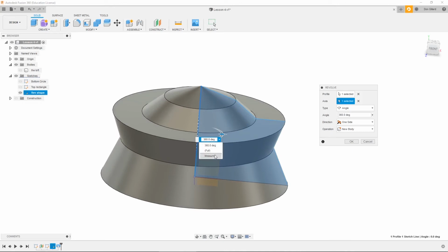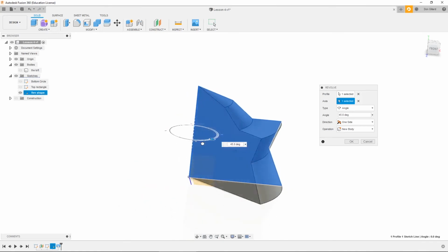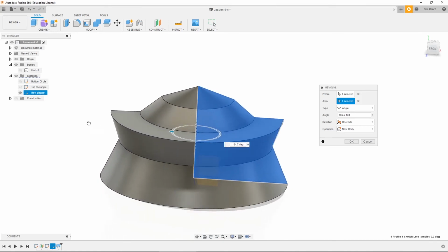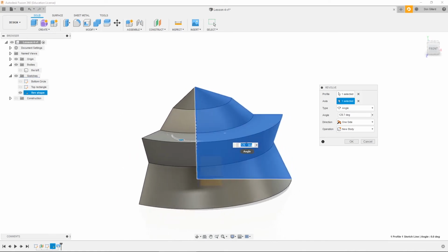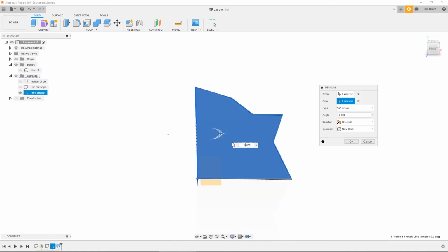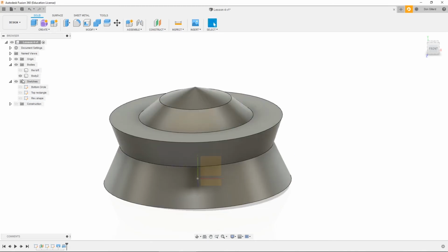Now the cool thing is we can actually do less than this. So let's say you're just having something come out of something, or you just wanted a pie shape. You can actually give it the amount of degrees. So 360 is usually what you want. Again, let's change this body to, sorry, not lofting, but revolving. Let's call this Revolve.